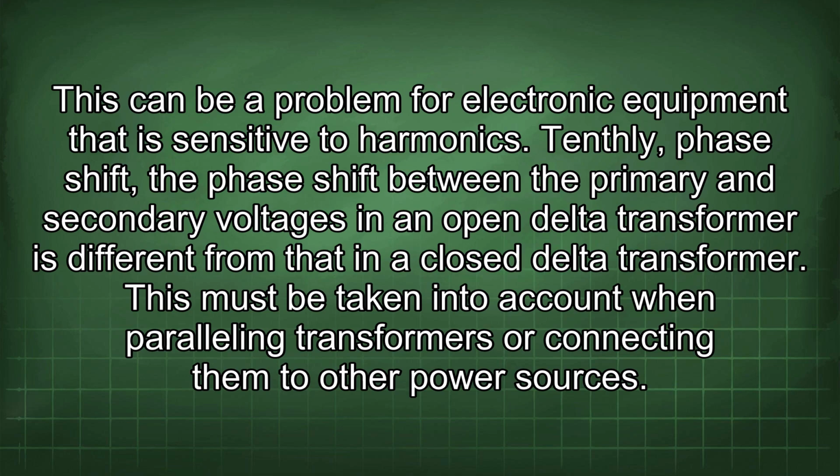Tenthly, phase shift. The phase shift between the primary and secondary voltages in an open delta transformer is different from that in a closed delta transformer. This must be taken into account when paralleling transformers or connecting them to other power sources.